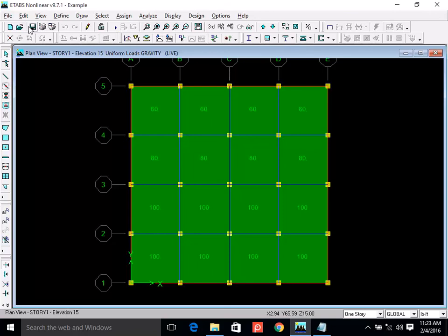When you are calculating the line loads from the drawings, you ignore the openings of doors, windows and ventilators. Okay? You don't have to be that precise, and you don't know, maybe in future they just construct the wall instead of window. You don't know about the lifespan. So whenever there is a wall, consider it as a solid wall. Okay? And you determine line load.